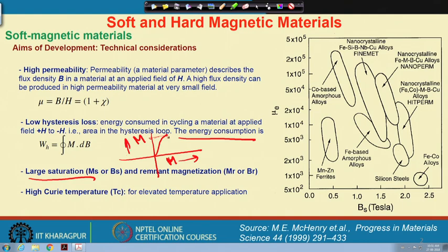This is the highest value where the magnetization saturates, called the saturation magnetization. After withdrawal of the magnetic field, at zero applied field some remanence magnetization appears, and that value should also be very high. This is a typical soft magnetic material characteristic.